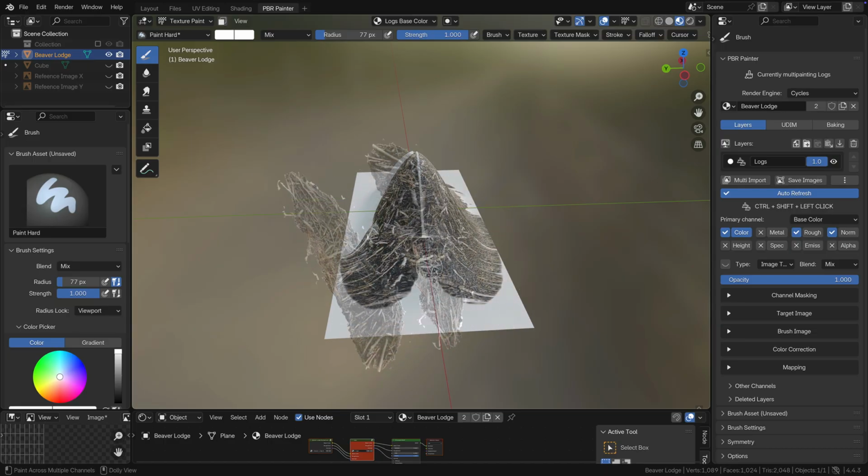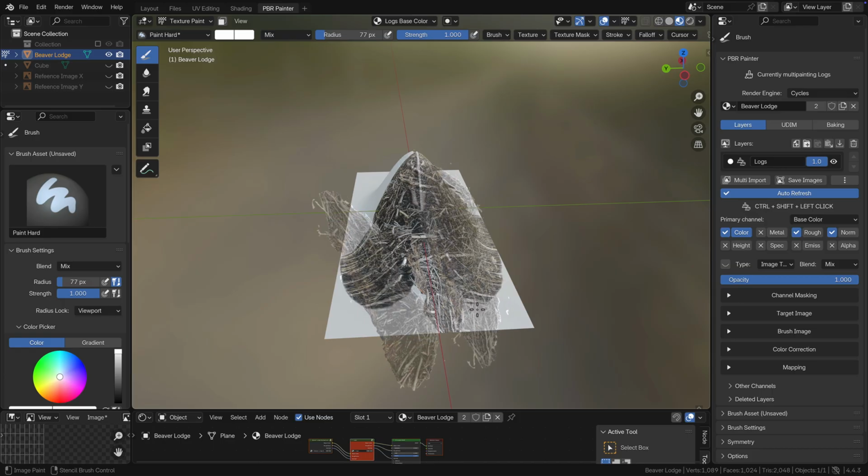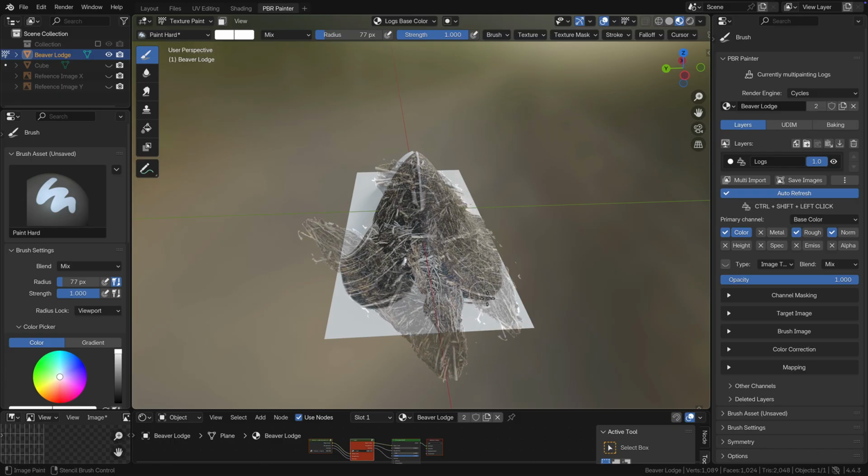Rightmost button dragging moves the stencil. Shift and rightmost button dragging scales the stencil, and Command and rightmost button dragging rotates the stencil. The brush size and strength can also be adjusted to paint the textures.